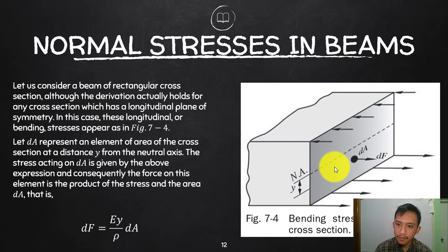So that's why from 0, your neutral axis is unstressed. So the stress there is 0. From 0 up to the maximum compression, and from 0 up to the maximum tension. So you can actually trace that as a triangular distribution of load. The distribution of load is not uniform, rather it goes from the biggest stress on the outer of the beam towards 0 at your neutral axis. So that will be a linear distribution of load.